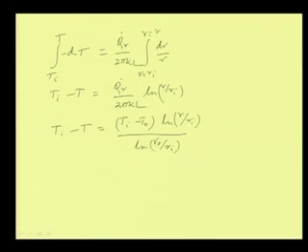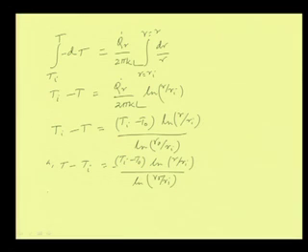by R I. So, this also can be written as T minus T I is equal to minus T I minus T O ln R by R I by ln R O by R I. So, this way you can get that T equals T I minus T O ln R by R I divided by ln R O by R I. So, this becomes the temperature profile within the cylindrical body, the hollow cylinder.